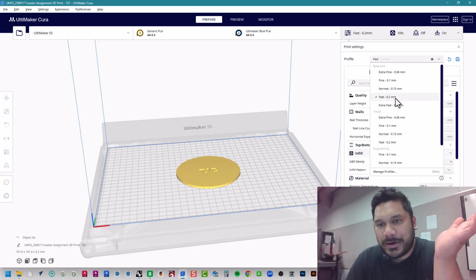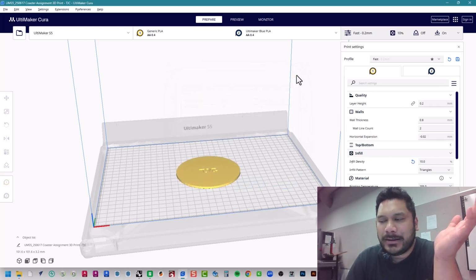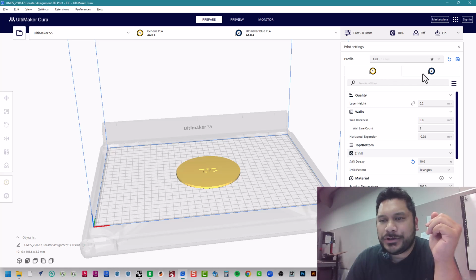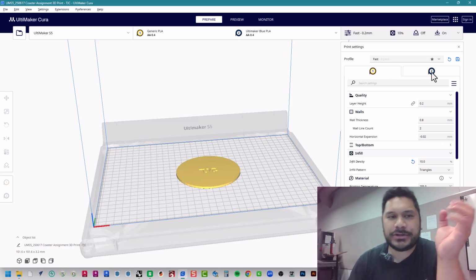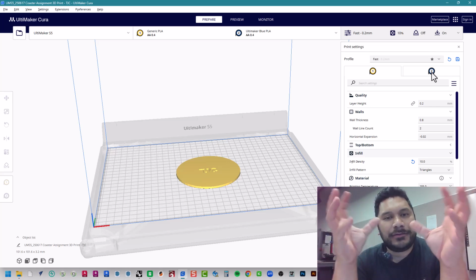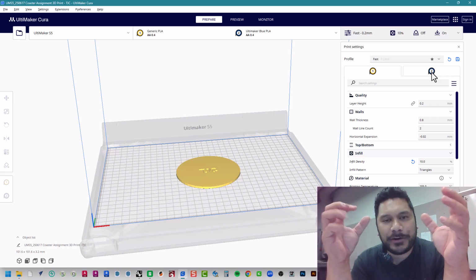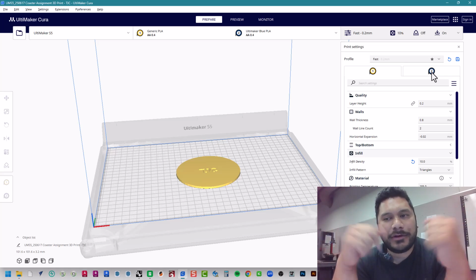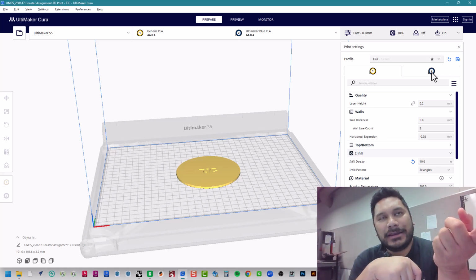You also want to choose which spool of PLA, because there's 2 possible spools that you can have loaded up on an Ultimaker, and this is where you dictate which one you use. So make sure you're looking to see which spool is there on the printers and which colors are there. Just because I choose blue here doesn't mean blue is going to magically walk over there and load itself up on those printers. You actually have to load these properly.